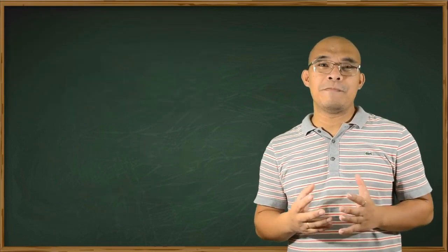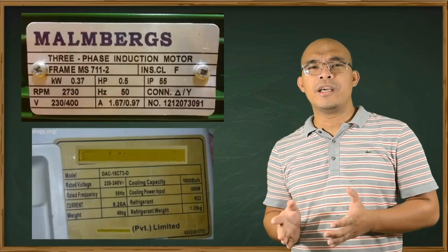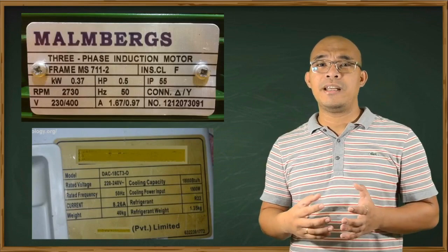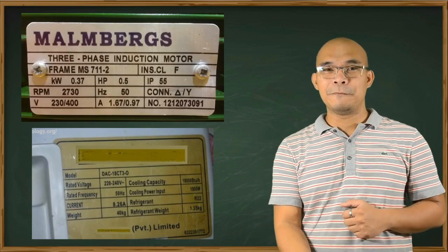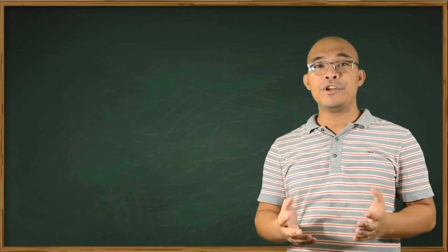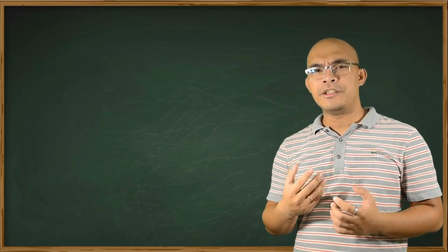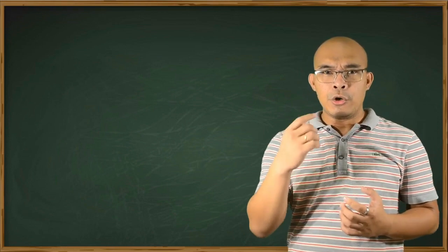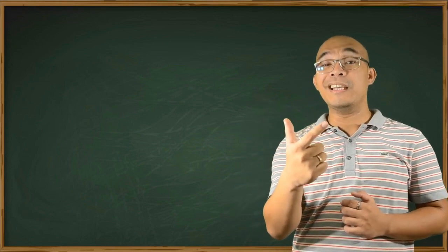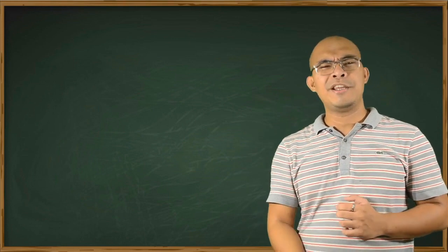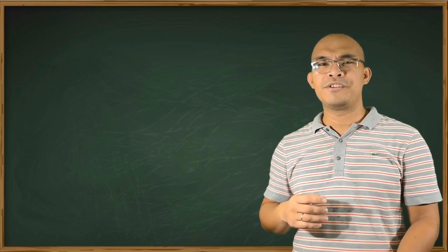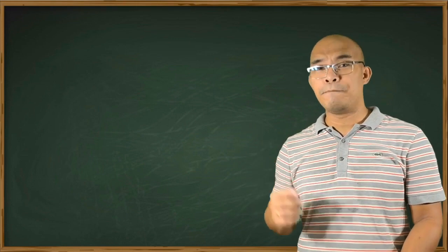Also, almost all equipment such as rice cookers, refrigerators, flat screen TVs, and electrical motors are rated using RMS voltage. So the frequency F, measured in hertz, of the generated voltage depends on the rotational speed of the prime mover and the number of poles in a generator. The relationship of frequency, rotational speed, and the number of pole pairs can be expressed in this formula.